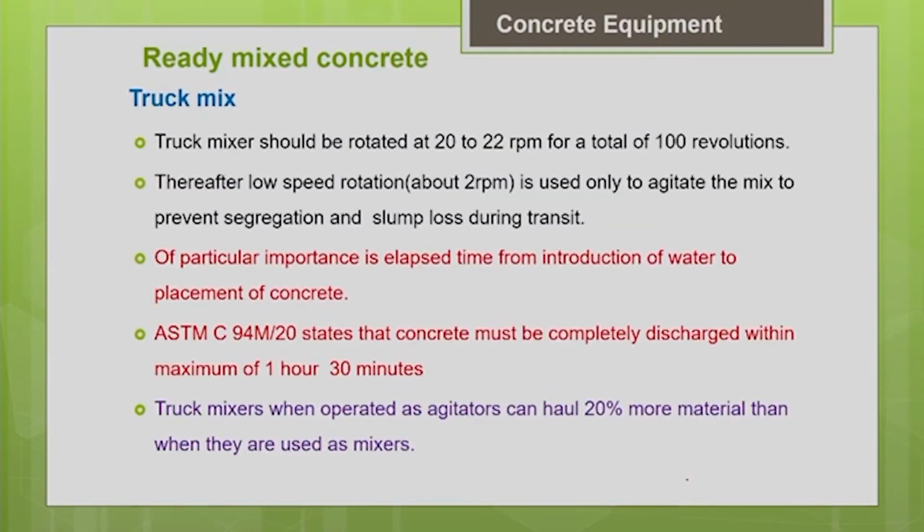If you are going for truck mix, in the sense that I am going to prepare the concrete inside the truck only, then there are some important guidelines to be noted. As you are going to prepare your concrete inside the truck only, you should rotate at a speed of 20 to 22 RPM.